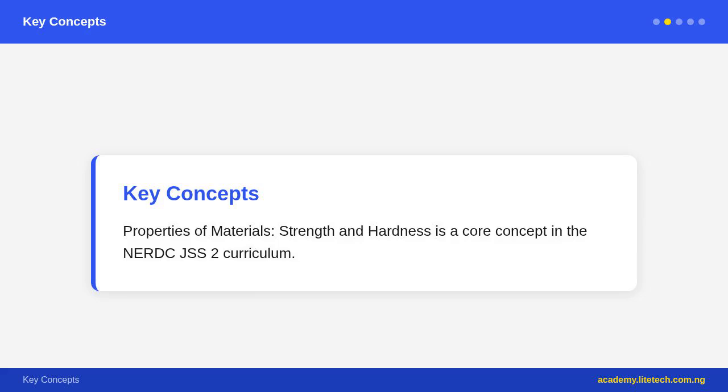resists this perfectly. Shear strength is the ability to resist forces that try to cut or slide one part of the material across another. Bolts and rivets must have high shear strength because forces try to slide the joint apart. Torsional strength is the ability to resist twisting forces. Drive shafts in engines and cars must have high torsional strength.